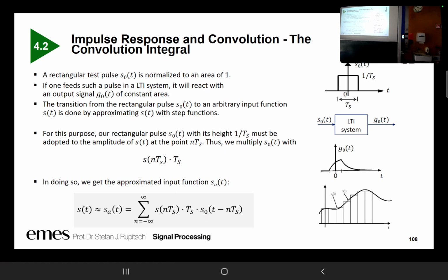But now we are only talking about the time. We approximate our signal with these rectangular pulses, amplified by the magnitudes. The time of the rectangular is always equal. We have to incorporate this time, and we do this with this factor ds. And here we have the scaling of the magnitude, and this is the basic rectangular signal S0, this elementary rectangle. We call it the elementary rectangular.